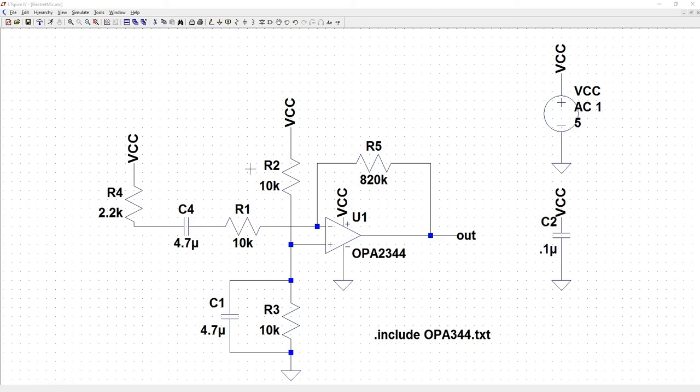Welcome to the 5th installment of Getting Started with LT-Spice. We are going to go over noise simulation. This simulation is a frequency domain noise analysis which includes shot, thermal, and flicker noise parameters. The result in units of volts per square root hertz is plotted to aid in circuit design analysis and your overall understanding. We're going to continue with the preamplifier circuit from the previous video.